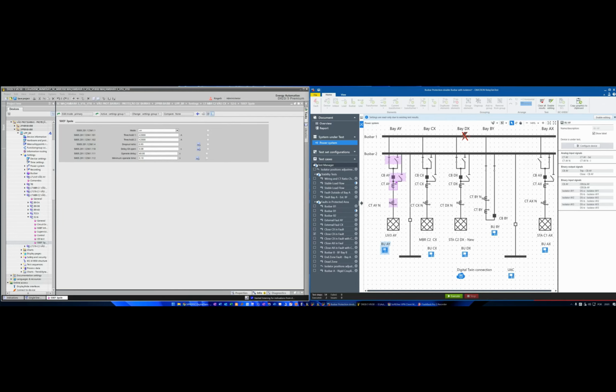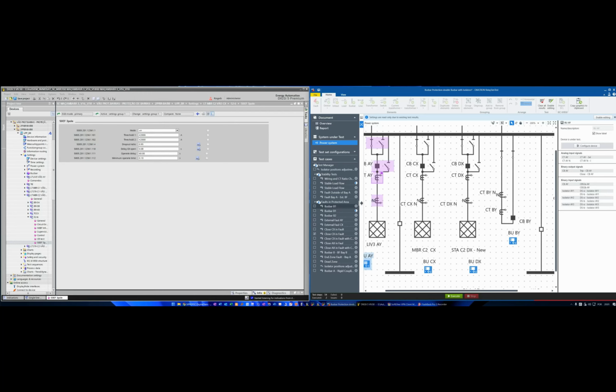So we have the end-fault protection logic to give a transfer trip to the remote substation here. But what is important, and why it is important for my busbar protection to see the status of the circuit breaker, is to know whether to put the current of my bay in or out.